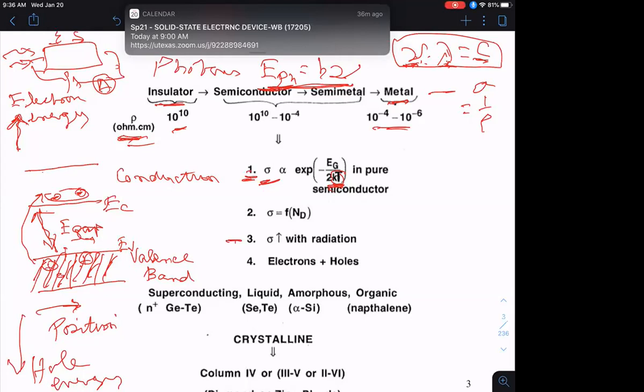All right. So going back to my band diagram, if I now shine photons with an energy h nu greater than this band gap, what's going to happen? Well, the same thing that happens with high temperatures. A few electrons will be excited from the valence to the conduction band. The more photons I shine, the more of these electron hole pairs are created, and the conductivity of the semiconductor increases. Okay, so this could also be the basis of a simple device, which is a photodiode or a photodetector.